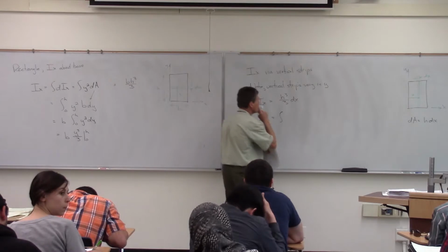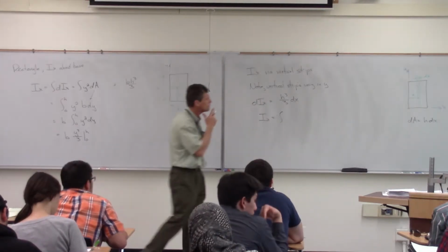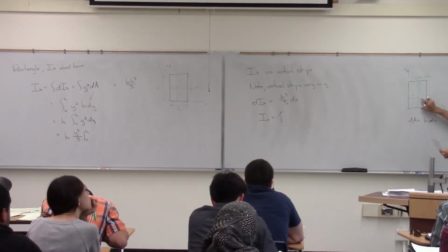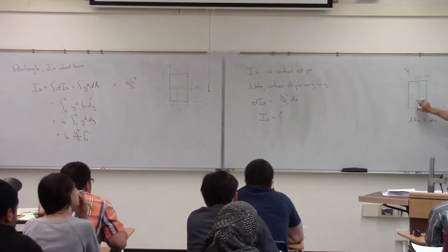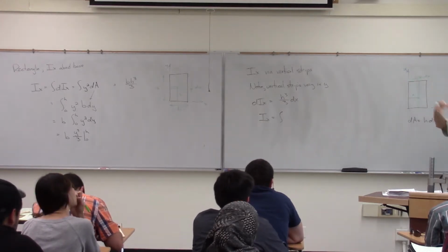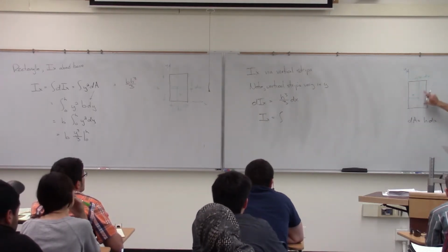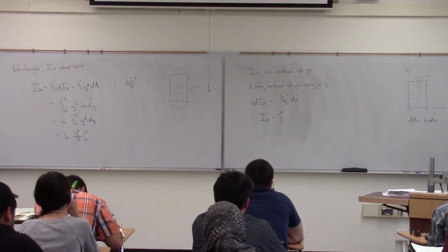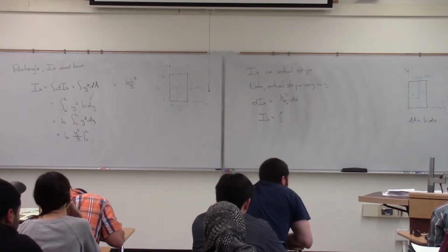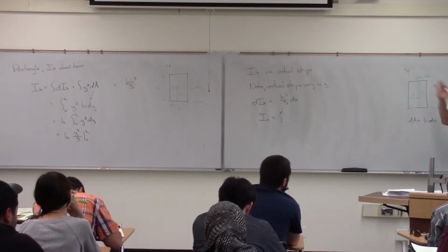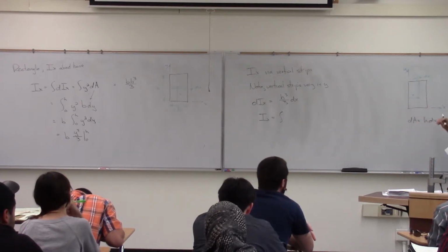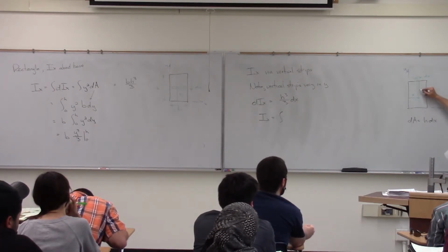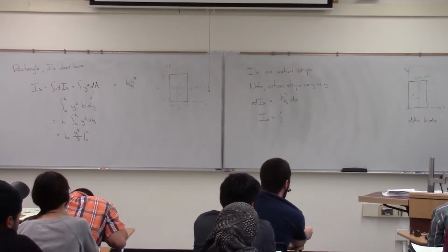How do the vertical strips vary in y? Question. Well, remember, what we're talking about when we do this moment of inertia is a measure of things that are going on at a distance away. When we were looking at fluid, how much force is acting out there. What we're talking about is how much area is away from this x. And this is basically what this moment of inertia is describing, and that's why we have things like eye sections and stuff. A lot of that material is way out here. So it varies in y when we think about that, because the y squared, anywhere I look on here, y is going to be different, right?